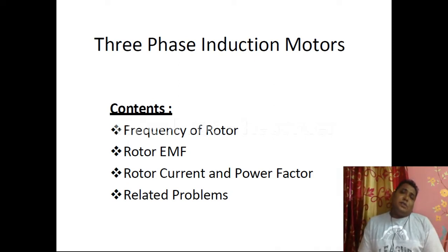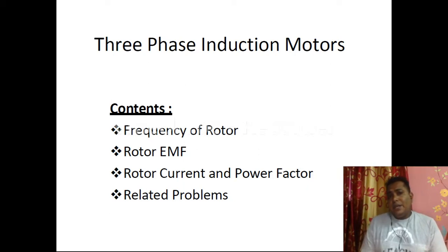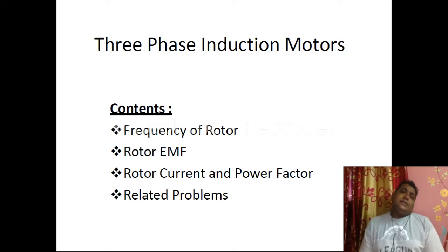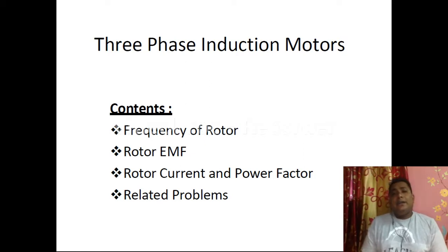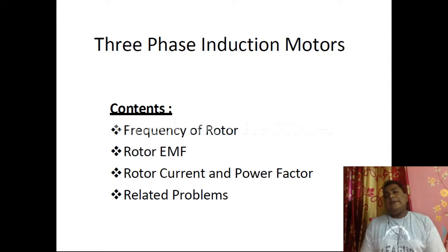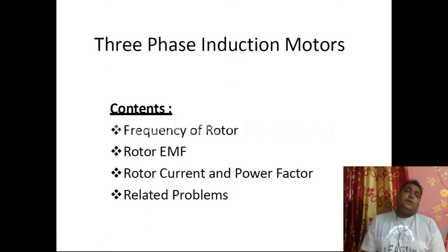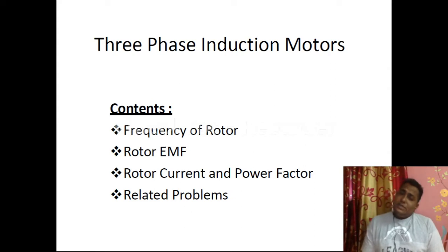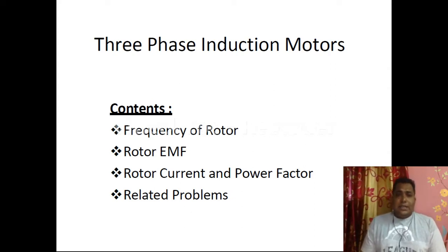In this motor we give electrical energy as input and take mechanical energy as output. A three-phase AC supply is given to the stator, where the field winding is energized, and the three phases generate three magnetic fields. The combination of these generates a rotating magnetic field, and if we place a rotor inside the stator, the rotor faces some forces and starts rotating. That's why the three-phase induction motor is a self-starting motor.